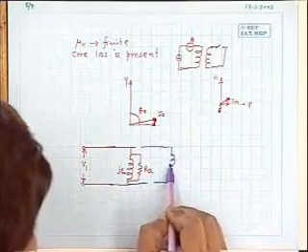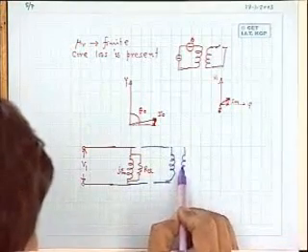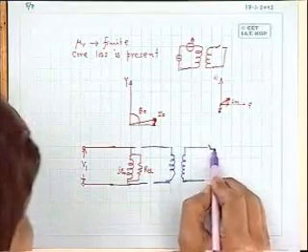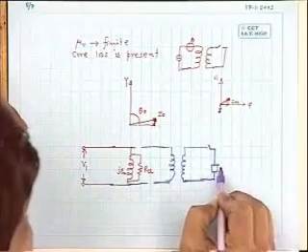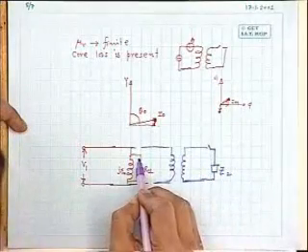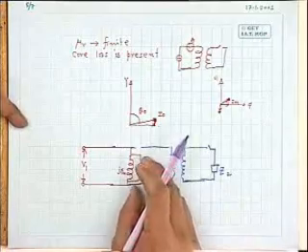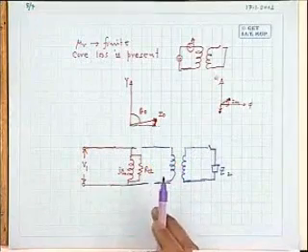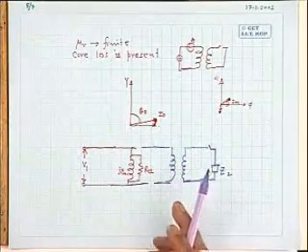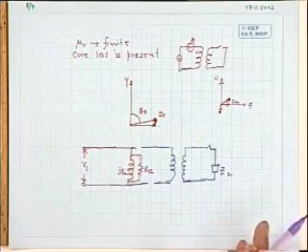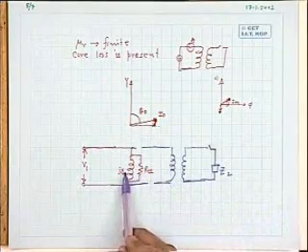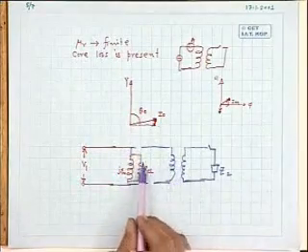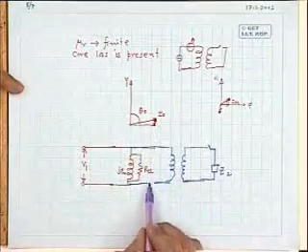And then of course, the rest of the things is your ideal transformer. Those things are there. And here is your load, whether the secondary is loaded or not. This RCL will have a constant power dissipated in it, because we have just seen the core losses are independent of the degree of loading on the transformer. So it should be represented by this.